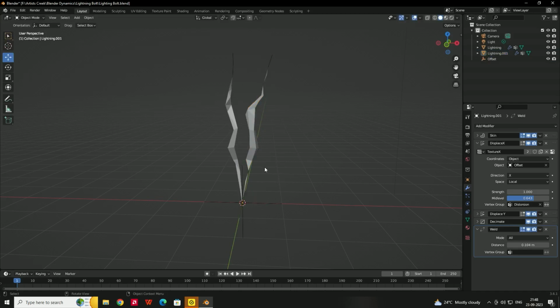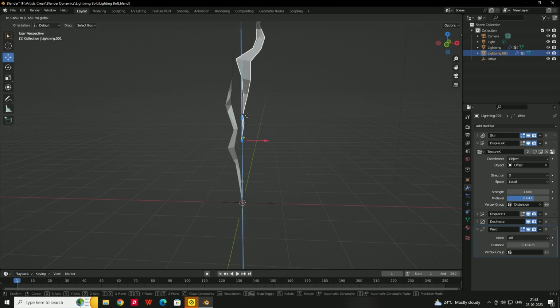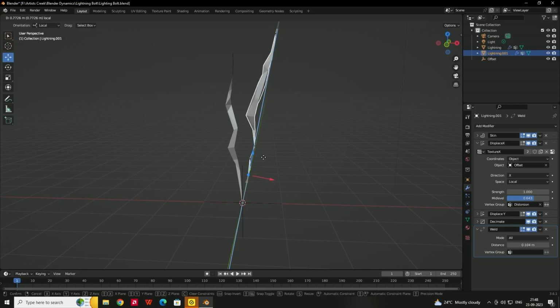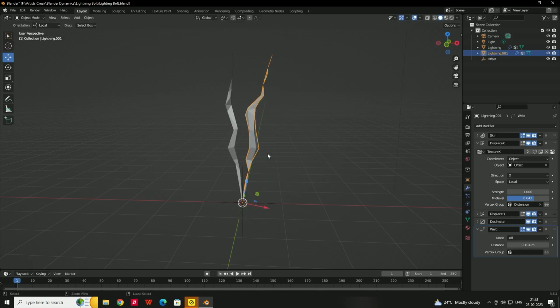So now you can give the animation for this, but we want the local direction, because see, now this is facing towards the world direction. I want the pivot point to face towards the local direction. In order to do that, we can select this orientation, and here you can select local, so that now we can make an animation in the local direction.